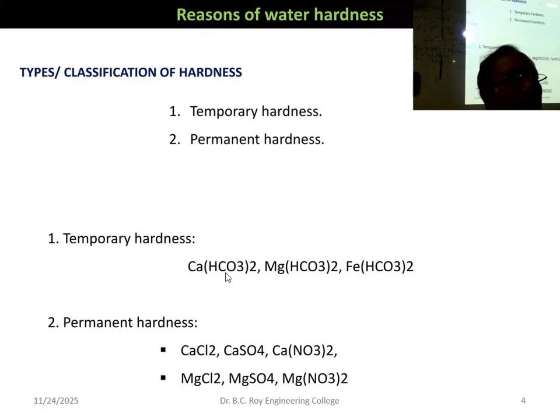That is actually carbonates. Because bicarbonate got converted to carbonate and it is insoluble, that's why it is getting precipitated. After that you are taking the boiled water from the top, decanting. Filtering is not a good idea. Actually, decantation is better because all these deposits are at the bottom. If you filter with cloth, 50% will pass through. But better to take the decantation because these are heavier, already settled down.